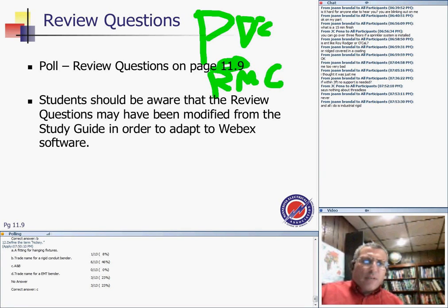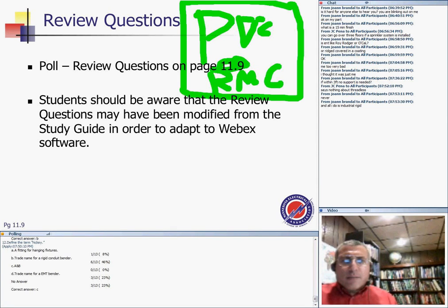We installed this in a wastewater treatment plant closer to the oxidation ditches and so forth. It's rigid with a PVC jacket all over it. We installed PVC-coated RMC in highly corrosive environments that also need physical protection.